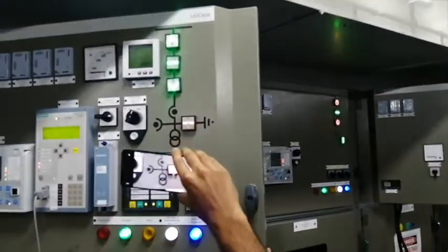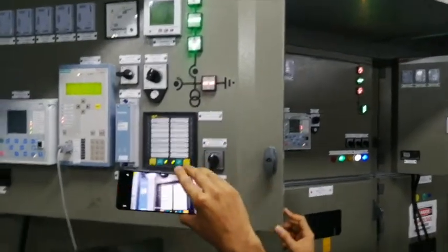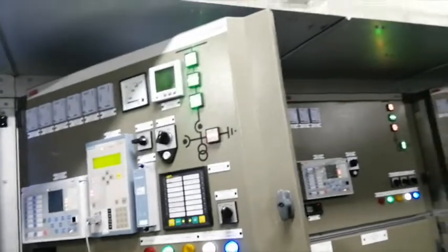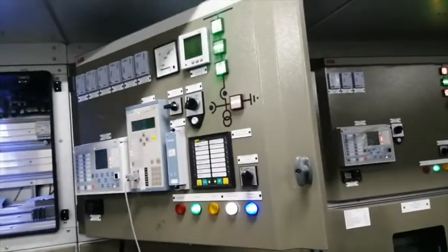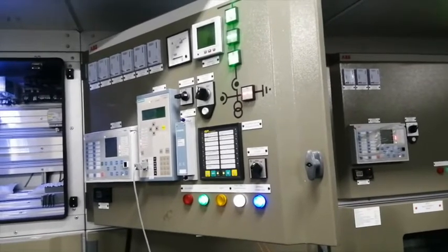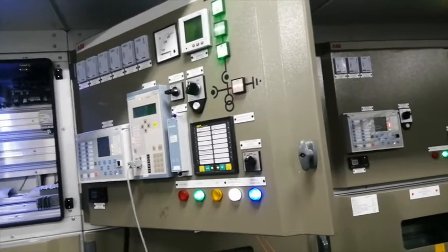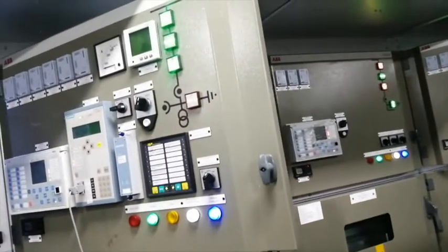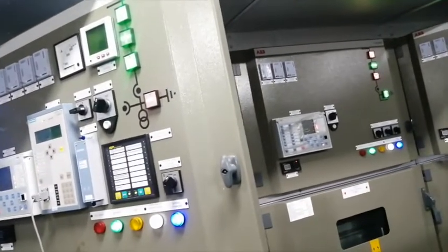It's red. So what we were checking is a signal from 11 kV switchgear to 132 kV switchgear. What was that signal? That signal was the permission to 132 kV side to allow the closing of 132 kV circuit breaker. But it was interlocked with the 11 kV earth switch. So if the earth switch on the 11 kV switchgear is closed, on the 11 kV incoming is closed, then we should not be allowed to close the 132 kV circuit breaker. So we'll check it. Do we have that permission or not?